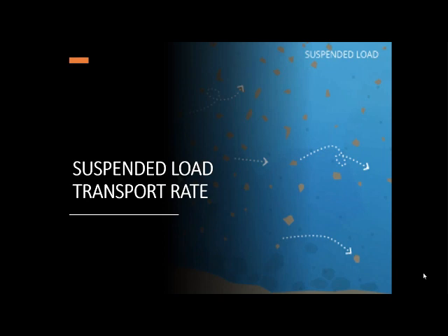But normally overall, bed load transport takes about 25% of the total load transport. So 25% of the sediment load in the river is bed load transport, and the other 75% is actually the suspended load.